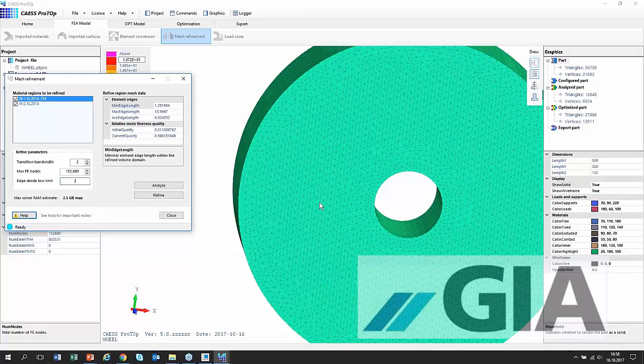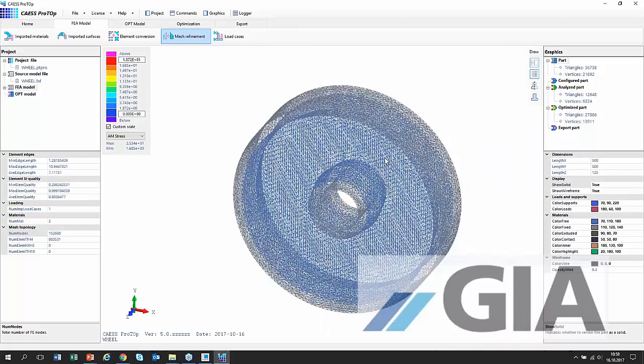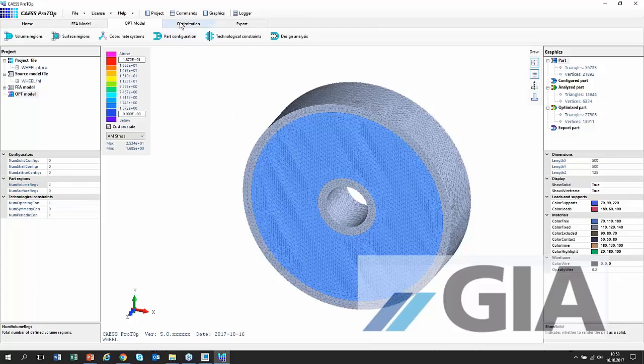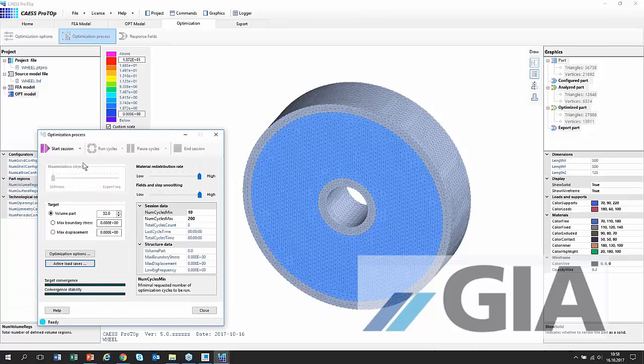We'll see, okay, the mesh gets much nicer, and that means our topology optimization will be much more precise. And I will go back for this optimization, and I will not start it from beginning. I will start it, let's say, from the last version, and here I can restart my session from this shape here with 33%, and I'm setting up here a new target.